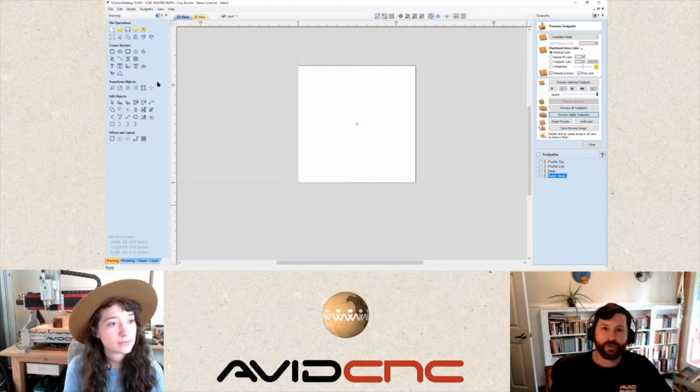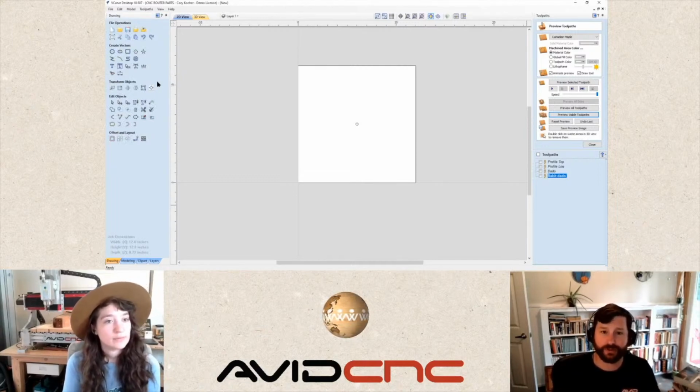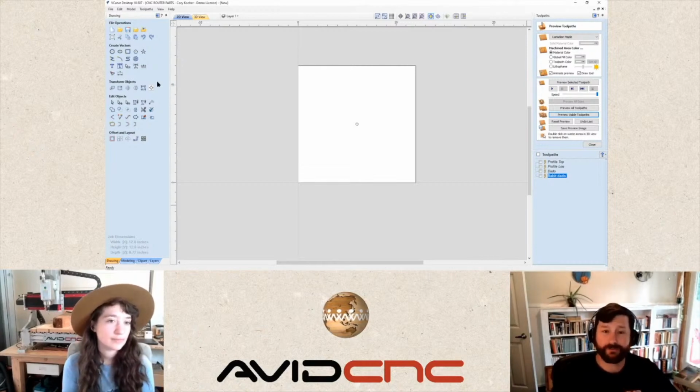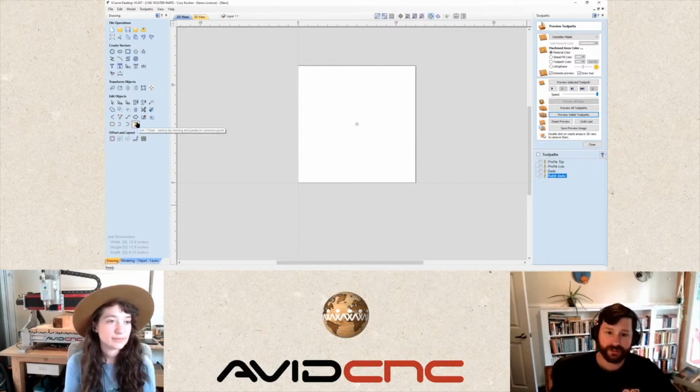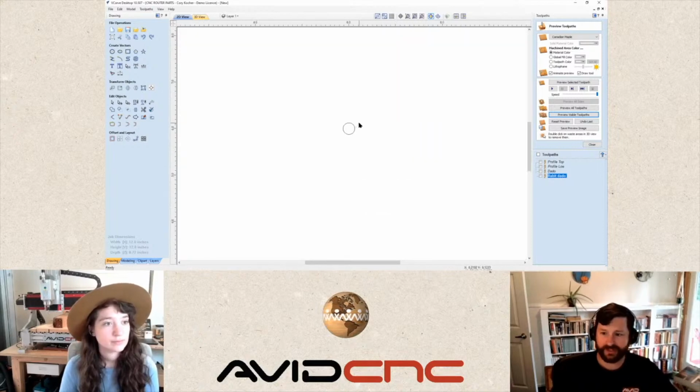Yeah, and so when we are using end mills to do drilling operations or to create holes, there are some strategies that I want to show you guys that I use that I feel are really helpful in getting chip evacuation and really extending that tool life and the cut quality. For this example, we're going to use a 1/4 inch hole as our goal. I have drawn a 1/4 inch hole here in the middle of our material.